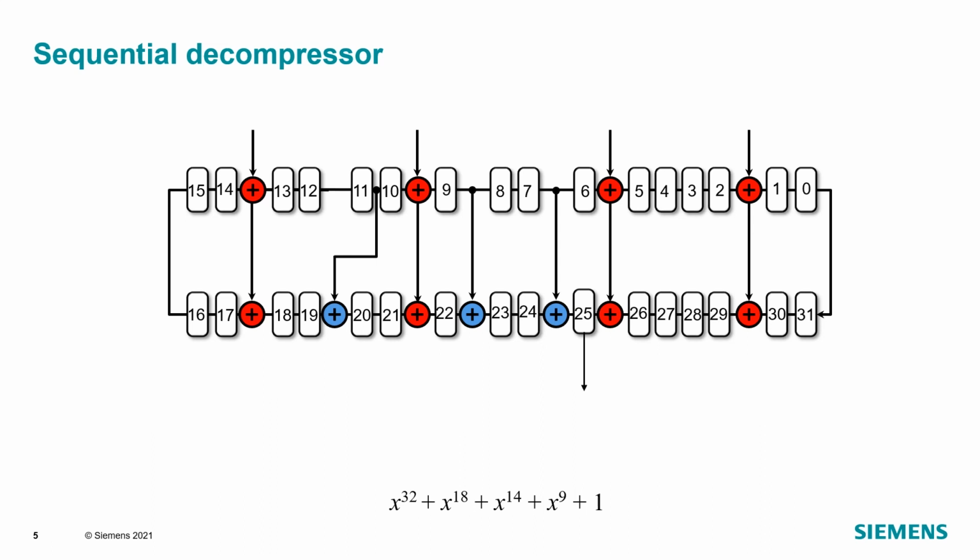It is now widely recognized that the latter offer the highest encoding capacity and efficiency. The other advantage is that they can perform a hybrid function as decompressors of deterministic patterns and pseudo-random pattern generators in logic BIST.